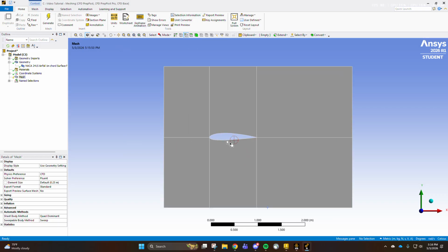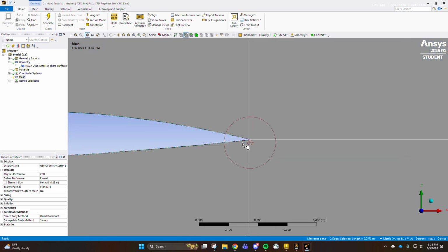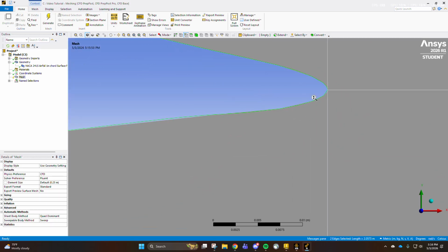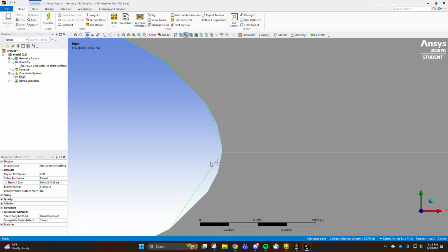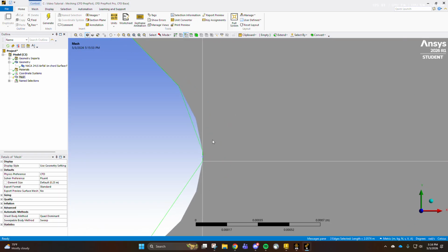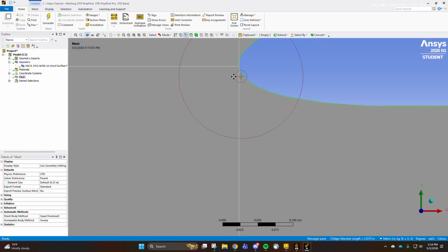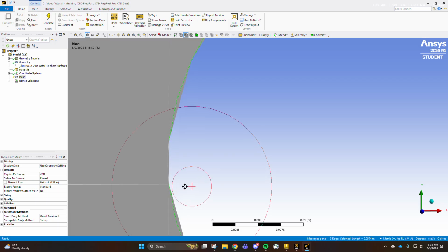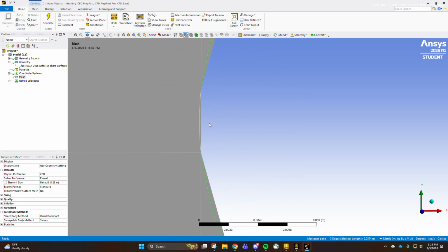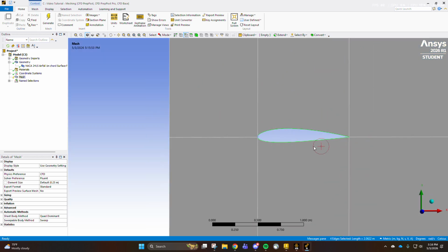So this is what the issue was: my airfoil is not just these two pieces. As you can see, if I zoom in, very slightly, there is a bit of the edge that intersects in this other section. And that was the reason my mesh wasn't great. Now, you're never really going to get it fully on the trailing edge. You can probably try and do it, but it's a little difficult. So it's okay because I was still able to get good results with this.